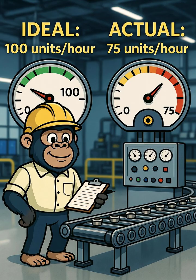Let's say your machine is designed to produce 100 units per hour. That's your ideal. But in reality, you're only getting 75 units per hour. Your performance score is 75 divided by 100, which equals 75%. So what causes performance loss?